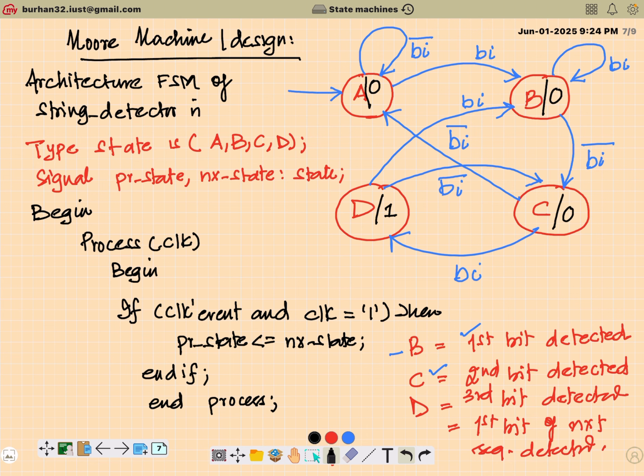And there will be some examples based on these sequence detectors, based on the counters, that you can do using the same method. So this is basically, like I said, a kind of framework or template for designing sequential circuits. There are multiple templates, but personally, I feel this template wherein we define a previous state and next state using a user-defined data type, then initiate a first process that defines your implied clock, then initiate a second process that defines the output in each state and the condition from which we can move the current state to the next state, is very trivial and straightforward.